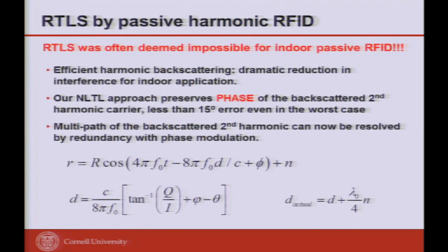On this one, phase in the nonlinear transmission line has one more surprising thing. As the phase propagates, I get a smaller phase noise in the second harmonic than in the fundamental. It's actually less than 6 dB. That totally confused me, and I haven't figured out why. Theoretically, if you have a phase noise and convert it to a second harmonic, you should get at least 6 dB more phase noise. But what I measure all the time is 3 to 4 dB. I don't know why. I tried all the experiments and theory, and I cannot figure out why my phase noise is actually small.